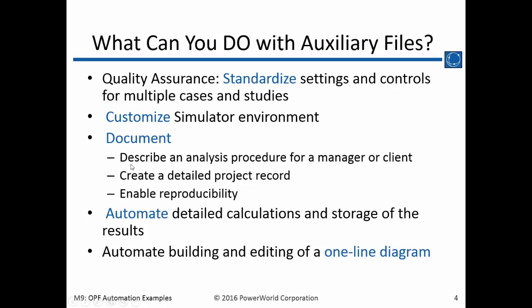If you do some parts of a study and you've got certain settings that you set up and you want to make it reproducible or show what you've done to a manager or to a client, if that manager or client also works in PowerWorld Simulator, you can put all your settings and all your assumptions in there, and then they can go through and see exactly what you did. You can document the whole process and what you did from the original raw file to the results that you generated.